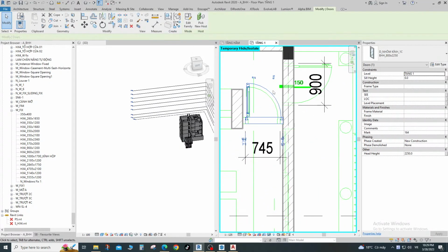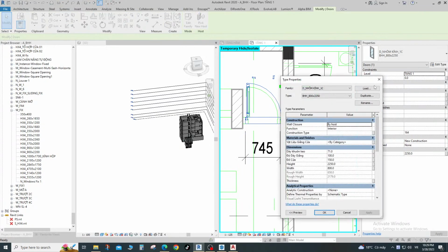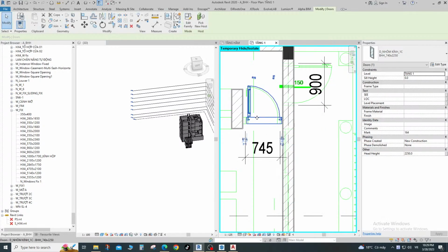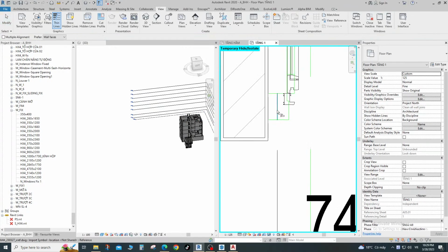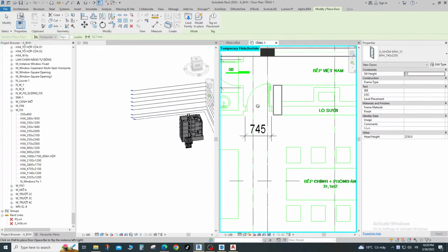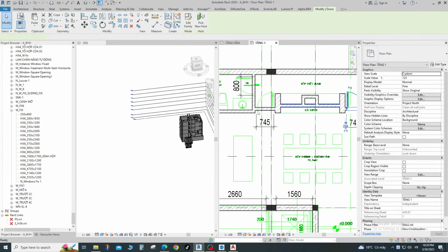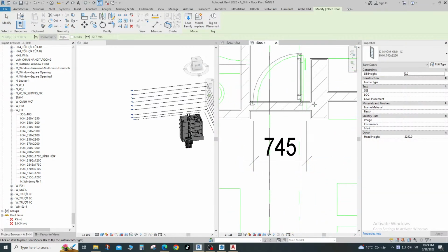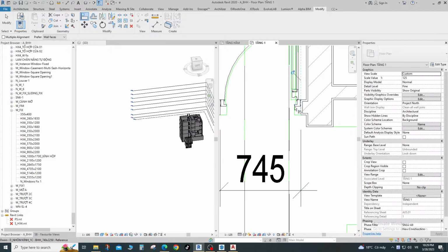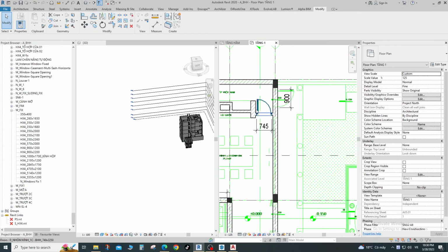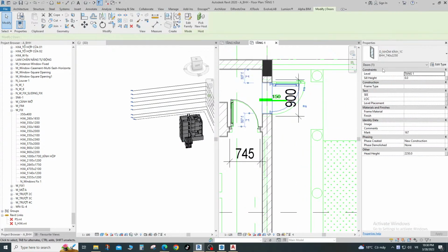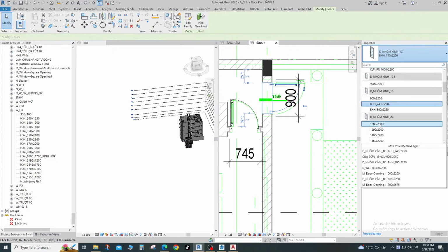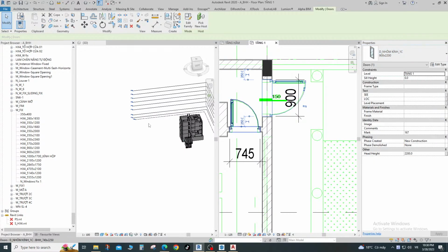So basically vertical. What I will do is, in case I need to place some vertical members somewhere here and here, I'll just copy the column there and then adjust the level. So for example, I'll change this base level to level 3, so it starts from this landing, and maybe stop at level 5, for example, stop here, and then we can just create from here. Oh, hang on. Yeah, don't worry about this. Let's ignore this part. Just pretend they all look like this one, and then with these columns, it's very easy to place framing.